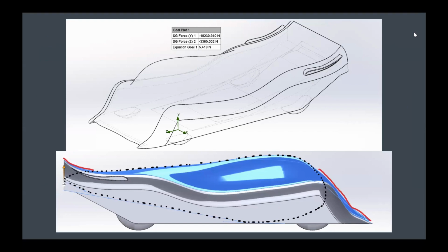And then here's a wireframe view of our car up top. And then down low, this is just an interesting thing we saw after we were fully done with design of our car and testing, that our car basically models the shape of a teardrop, which is the most aerodynamic shape. But it has two spoilers, one in the front and one in the back. And the front spoiler basically deflects all of the air away from the part of the teardrop that would be generating lift, because it has that sort of positive slope where if the air connected with it, it would deflect down, causing our car to lift up. But we sort of negate that part of the teardrop, but hold many of the benefits of its streamlined effect.